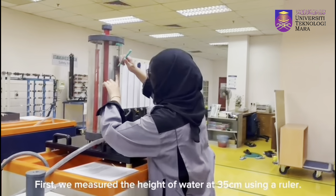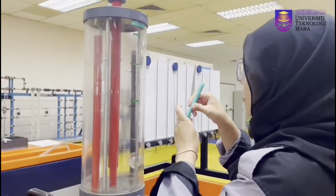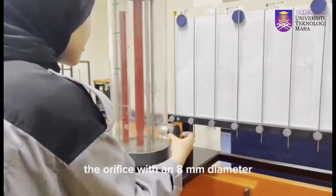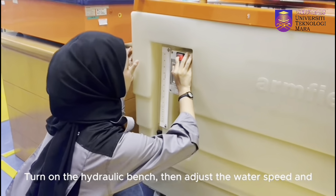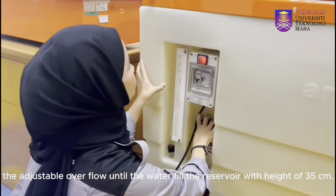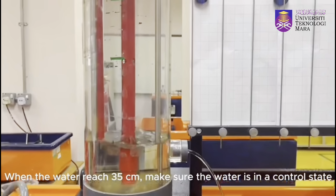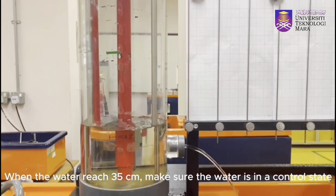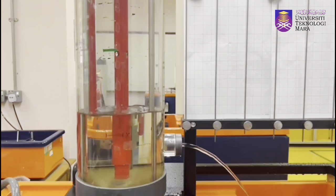First, we measured the height of water at 35 cm using a ruler. The orifice with an 8 mm diameter was placed at the tip of the reservoir. Turn on the hydraulic bench, then adjust the water speed and the adjustable overflow until the water fills the reservoir with height of 35 cm. When the water reaches 35 cm, make sure the water is in a controlled state without wave and remain at the same height until the reading is complete.